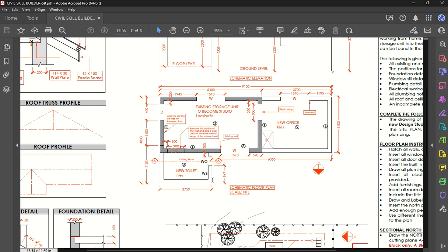Now, in order to start this, we're going to work with the full perimeters of the external edge of the wall. So we've got 9.1 by 3.1 by 6.350. We're not given a perimeter marking for this. That's fine, because we can come back to the top corner here, go down 4.803, across 2.750, and then quite simply go back up and meet on that point.